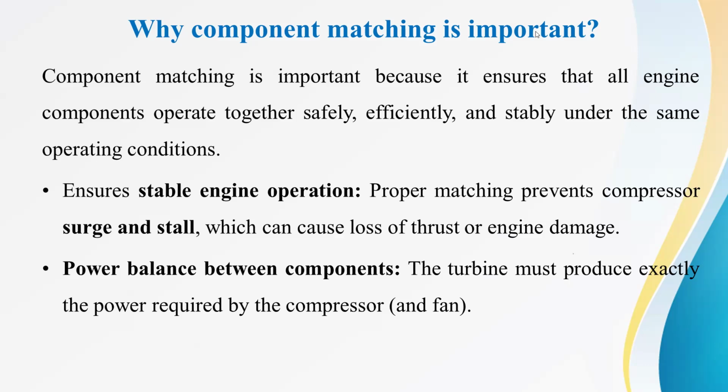Stable engine operation is related with proper matching, which prevents compressor surge and stall. Again, power balance between components is required. The turbine must produce exactly the power required by the compressor and by the fan. So power balance is another reason why we are performing component matching.